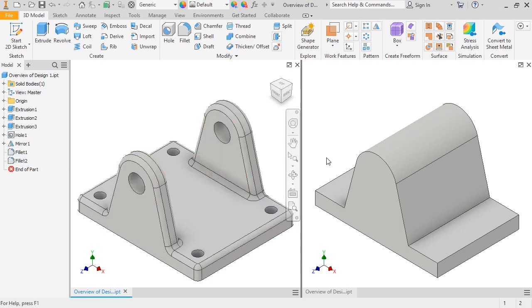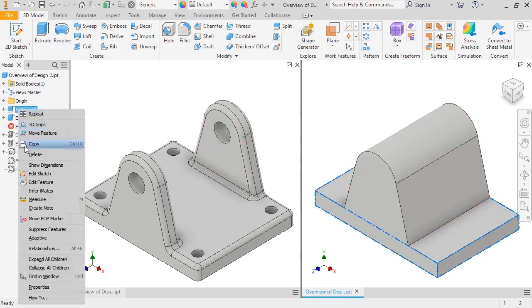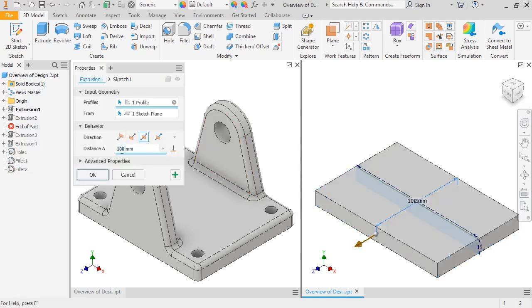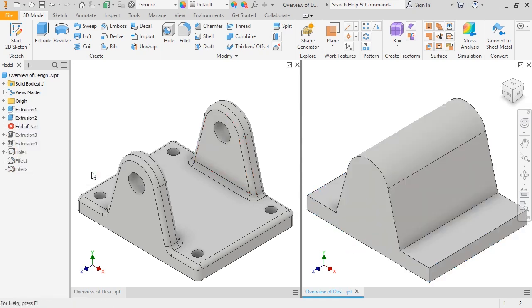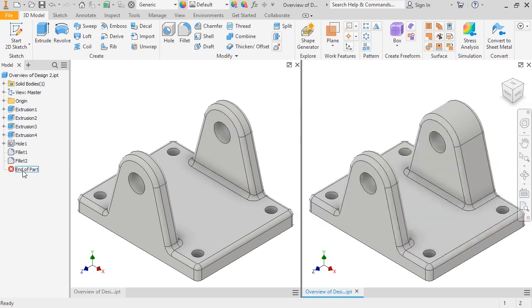When I repeat the same edit on the extrusion heavy version, however, the far side tab gets thick. This is because when I created the sketch that cuts out the middle area, I defined it based on a single side and middle distance value. To make this update the same way, I could change how it updates by defining the cut area from each side, rather than a middle distance.